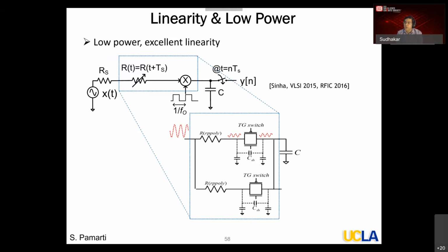So what we have tried to do so far, and I'm not saying this is the only way, is to come up with resistor DAC structures which try to minimize the parasitic capacitors' time variation. We try to make sure that the parasitics that are varying in time are minimal. We don't mind if a particular capacitance is fixed. Definitely, this is not trivial by any account.